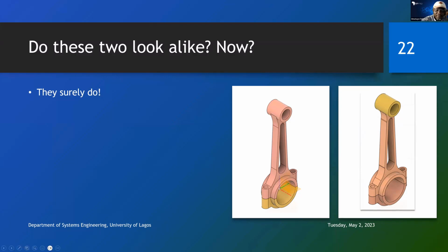Any reason? I'm still waiting. I'm in the chat room waiting, looking at you. I think it depends on the size of the crankshaft. No, it doesn't depend on the size of the crankshaft. Both of them will fit. Whatever crankshaft this one fits, this one will fit it exactly. Both of them, because what will determine that is the internal radius of the big pin.